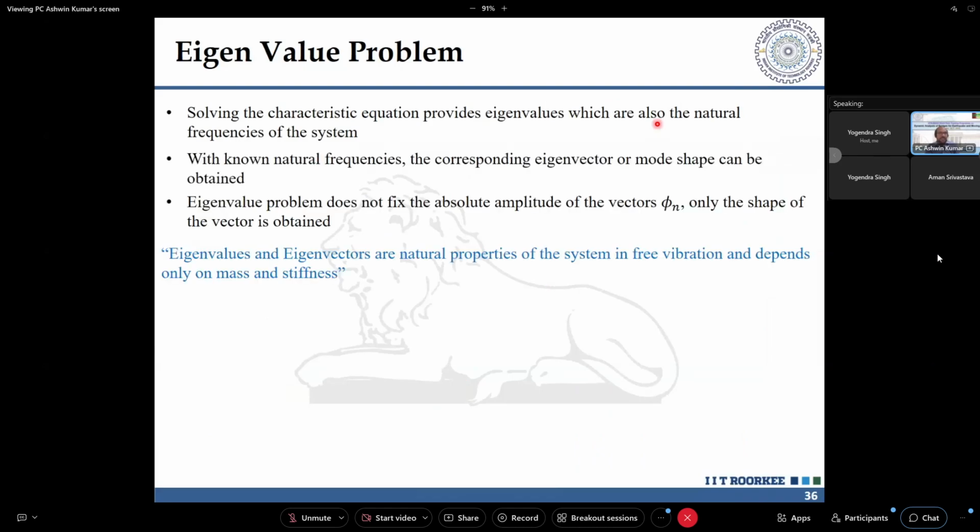So the eigenvalue problem, what I said earlier, gives you the characteristic equation which you solve to get the eigenvalues and eigenvectors. It gives you a sense of what are the different masses that you have lumped. It's your choice, right? The eigenvalue analysis that the Midas software or any other software does for you depends upon how you have modeled the structure, what are the free nodes, where you have put the masses, and what masses you have put.